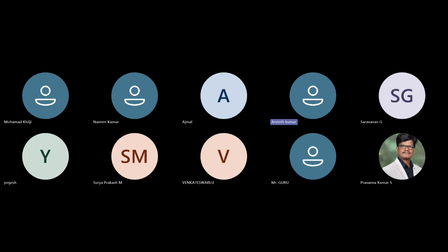Like the OS we are going to infuse into the board itself? Yeah. We are going to convert this normal STM board into an RTOS-specified board, a real-time embedded board. There will be some APIs. There are multiple OS providers for RTOS. One such is FreeRTOS, an open source program for a real-time operating system. We'll be using FreeRTOS for configuring this STM board, and we are going to use their APIs.